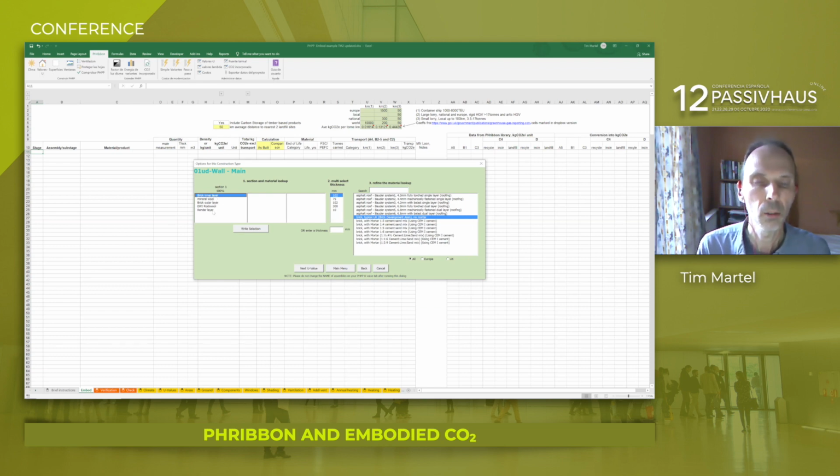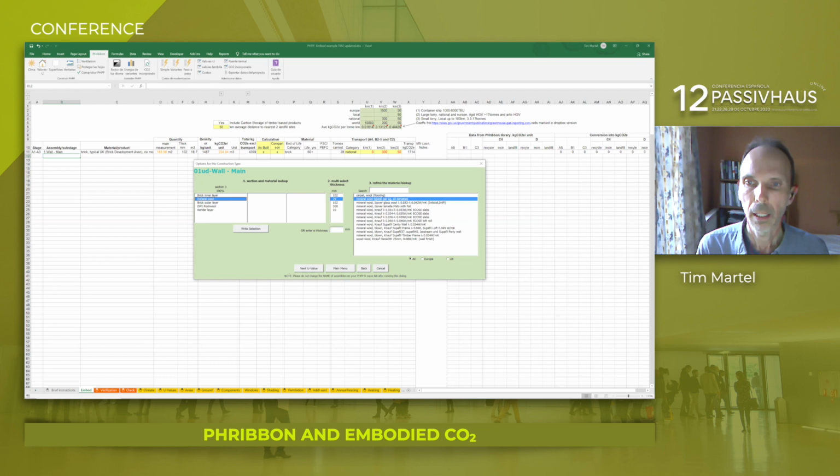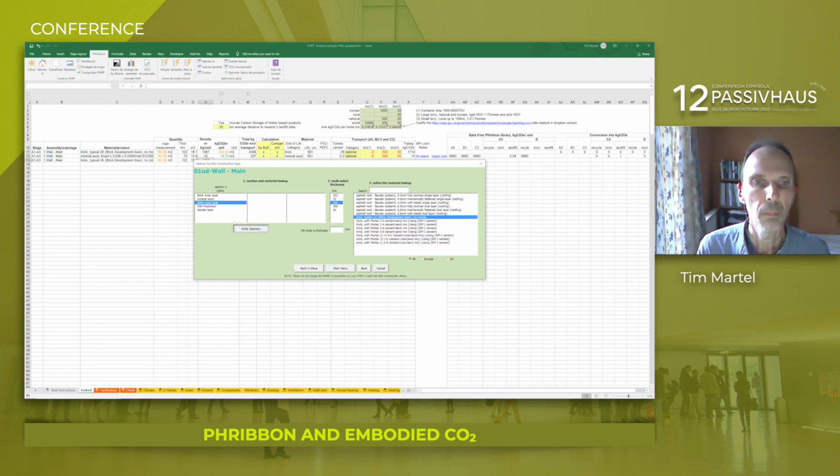These are the materials that it was showing us before for this U value, and it's matched this one up with these in its library, and that's not a bad choice there, so we can write that one and it'll start writing that selection. This mineral wool one, we can specify that one, and then this brick outer layer, that'll be the same as that one.